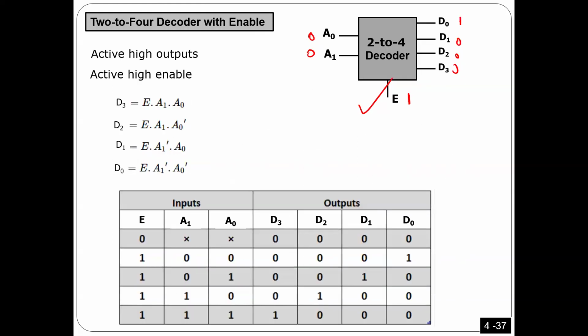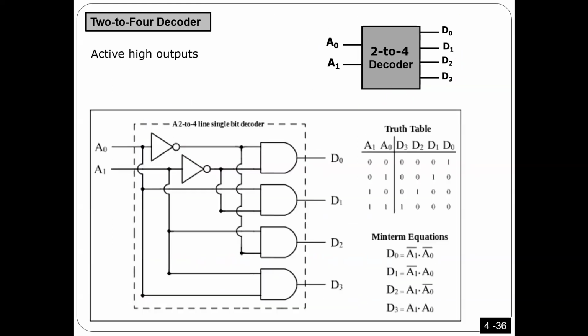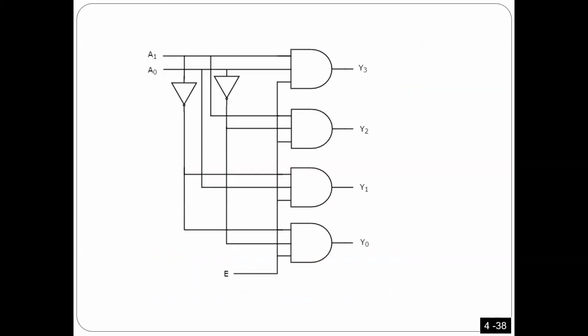And actually what I did was something very simple. If this is a decoder, I just added one more input here. That's what I said last time. I added just one input here for the enable. That's it. So if the enable is 0, every gate is going to have 0, so all of them are going to give output 0. That's what I mean. Okay? So regardless of what input you have, all of them are going to give zeros. Okay? Very interesting, right?